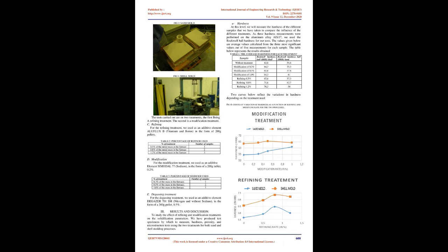Production of test specimens. We cast different specimens allowing us to subsequently perform the various tests, which are a micrographic analysis, the recording of thermal curves, tensile tests, hardness tests, chemical analysis, and measurement of the porosity rate. B. Material available. To make these specimens, we heated the hypereutectic Al-Si17Cu4 alloy in an induction furnace.